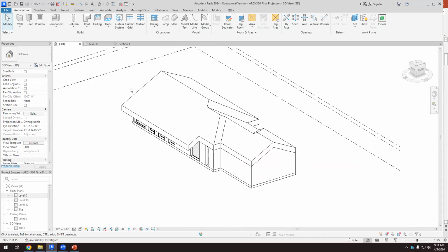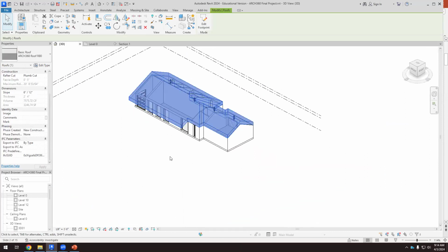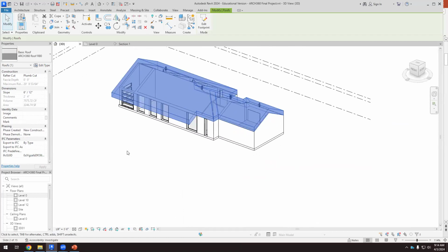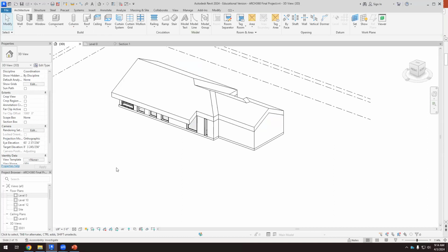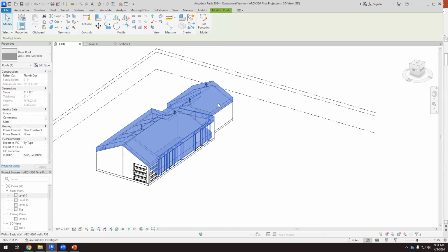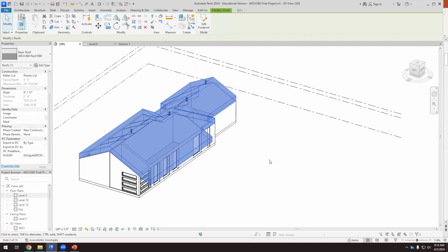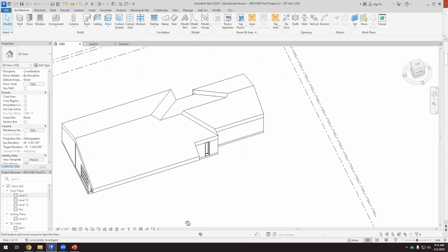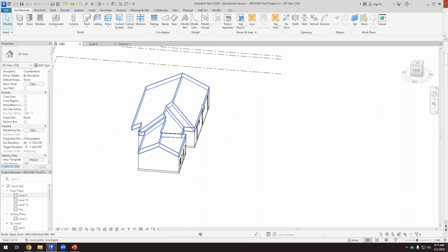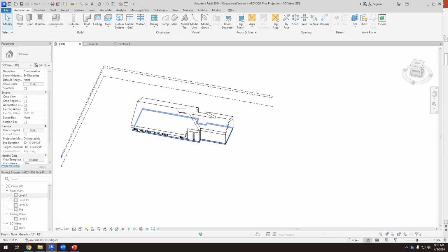So we have a nice roof area facing south, okay? And part of this roof area facing south will be covered with PV panels, and we need solar collectors. So this is what we need now. We need to identify the surface that we can have exposed to solar collector, the part of the roof that is occupied by solar collectors and the part occupied by PV panels. If part of this roof faces south and part faces north, forget about the northern roofs. So we have to use only the south.